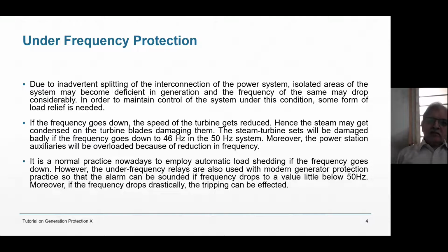The speed of the generators will increase, meaning on one side there will be over frequency, on another side there is under frequency. Or otherwise you are joining an abrupt load to the generator, or load is more than generation, then also under frequency will occur. Nowadays, on a 66 by 11 kV substation, some 10, 11 kV feeders are outgoing.